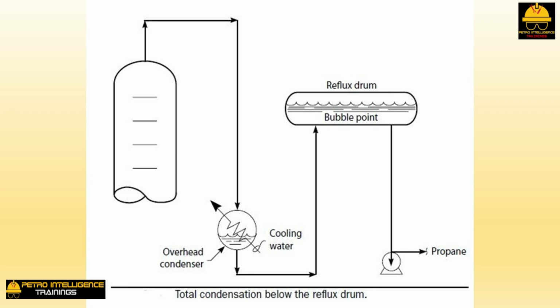Perhaps a small amount of heat transfer would take place as the liquid propane became subcooled. But none of the propane vapor would condense. Therefore, the liquid level in the overhead condenser would have to be somewhere in the condenser's shell. But then the liquid in the condenser would be below the reflux drum. How, then, does the liquid get from the lower elevation of the condenser to the higher elevation in the reflux drum? We will have to explain this hydraulic problem later.